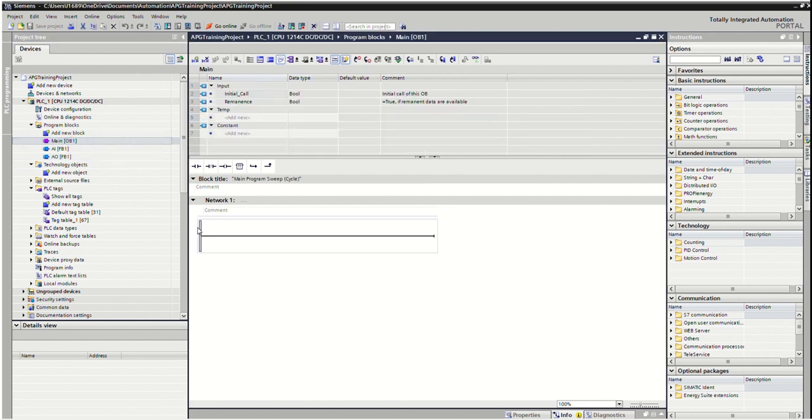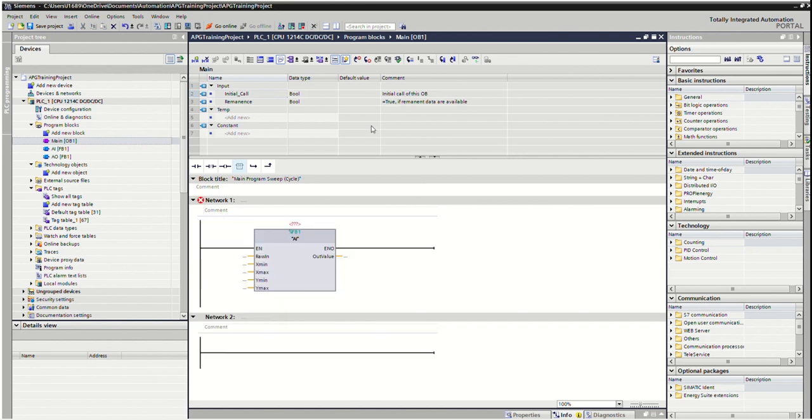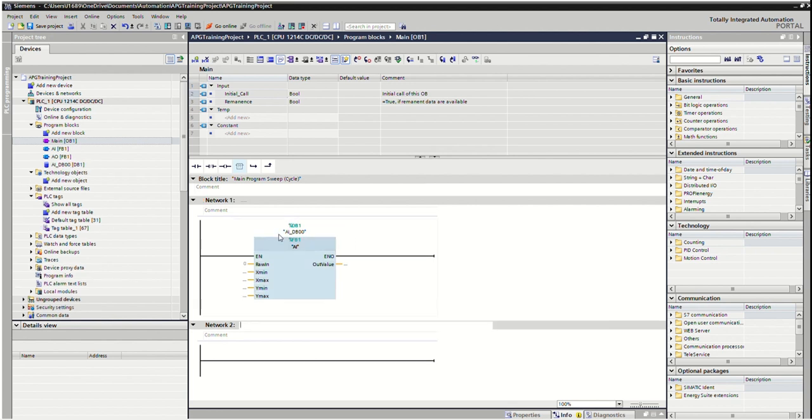Here we can use that function block as analog input and analog output blocks. Just select the raw block, and here we can assign AI. It will automatically assign to the function block of AI. And the data DB, it automatically assigns when we create the data tag name for that AI block. Suppose the tag name is AI DB00, then it will automatically assign to DB1,